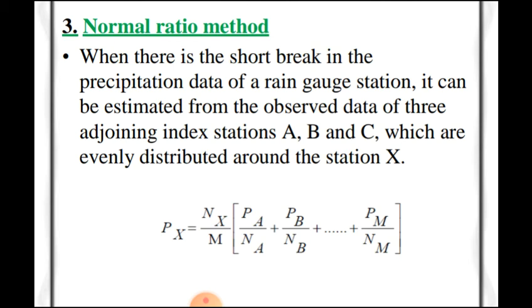If you want to design something very safe, we should go for 100 years precipitation. For this 100 years precipitation we can find out what will be the depth of precipitation, and those curves we can prepare in terms of duration, depth of rainfall, and the time period.